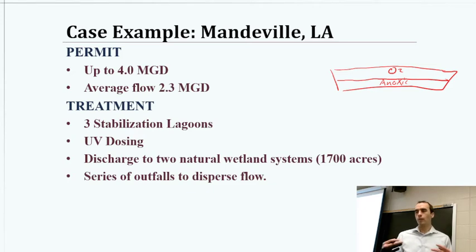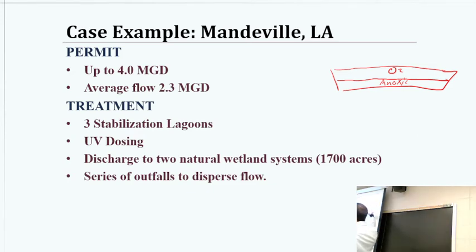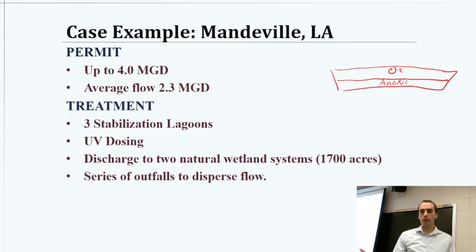So in some sense, stabilization lagoons are relying on a combination of aerobic and anaerobic processes and some interesting biochemistry at the interface there to do a lot of the processing. And then you just give it a long time sitting in there, right? So that you get a fair bit of treatment just putting it into a lagoon and letting it sit.